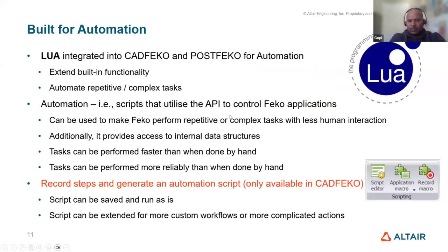So apart from all those different solvers as well as solver features and optimization built into Feko, if you want to automate something, then that is also possible using Feko. Okay? So we have Lua scripting built into both the preprocessor as well as the post-processor of Feko, where everything that you can do from the graphical user interface, you will be able to do from a script. Okay? So using Lua scripting, you can automate everything that you can do either on the pre-processing side or on the post-processing side.